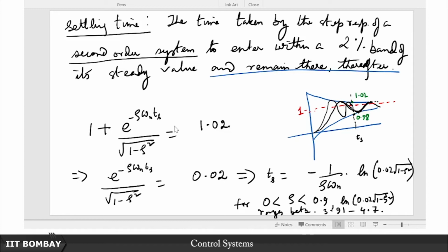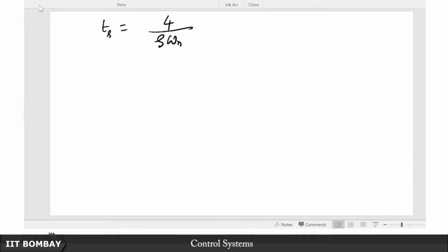They really do not. From the interpretation of the pole itself, we've seen the rise time depends on the magnitude of the pole, the settling time depends on the real part of the pole, right? And also physically speaking, one tells you how fast a system responds to the application of an input, which is the rise time. The other tells you how fast the transients decay and the system settles down to a steady state. That is the settling time. These were not very easy to describe when we were only talking about first order systems, but now with second order systems, I hope that you begin to see the connection and the reason why we have these two different metrics, independent of one another, the settling time and the rise time.